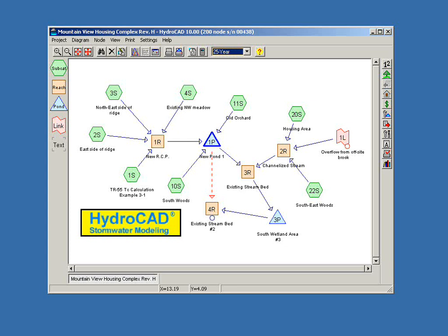We're then going to talk about the orifice outlet. We can have an orifice in a horizontal or vertical orientation, and we want to talk about what each of those means. An orifice can also handle weir flow under low head conditions, which is something we need to look at. And then there are special provisions for modeling grates and flow around the perimeter of a grate. So that will all be in the orifice section of the session.